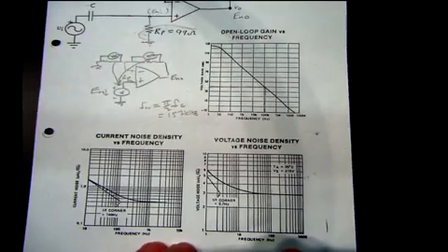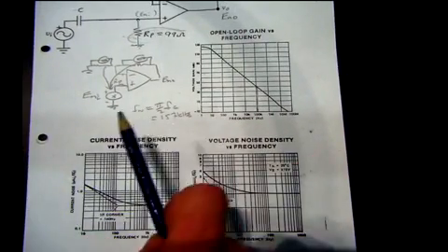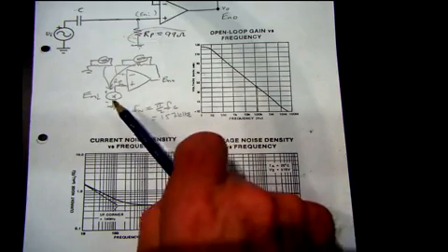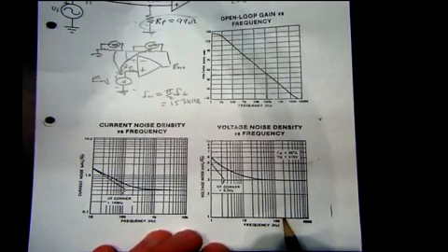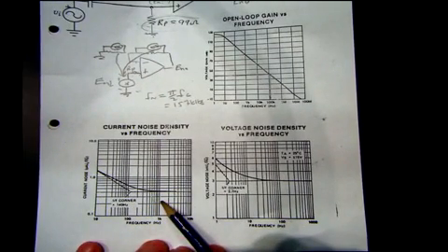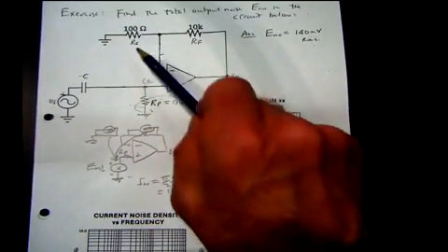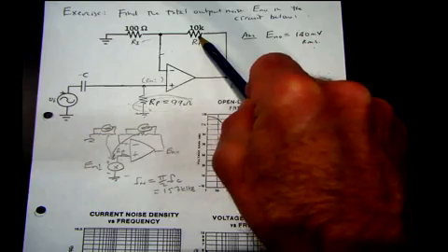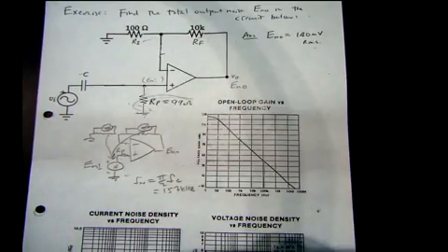There'll be contributions from noise voltage, as we talked about before, plus noise current that's conveyed through the resistors, and it's going to be this resistor plus the parallel sum of those two, which works out to be just on 200 ohms or 198 ohms.